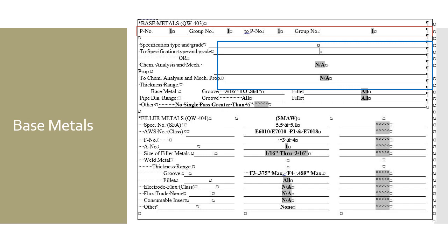I think about 25 years ago, I could be wrong, a bunch of materials went from being P5C, and I think they became P15E. That's a bunch of these high temp creep resistant materials, if my memory serves me. But anyways, there got to be enough of them, and the people in ASME decided this stuff's a little different than what we previously thought. It gets its own P numbers. So that's what the P numbers are.